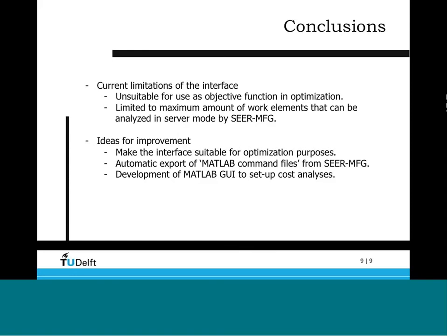And another thing that could accompany such a thing would be a user interface in MATLAB, where you can also set up your cost analysis using the basic command file that you created in SEER. And then you can, for example, import this basic command file in MATLAB, and you could set some settings like the range of length that you want to analyze, or the range of the width of the stringer that you want to analyze in the optimization.